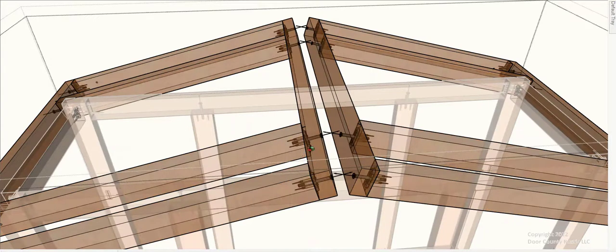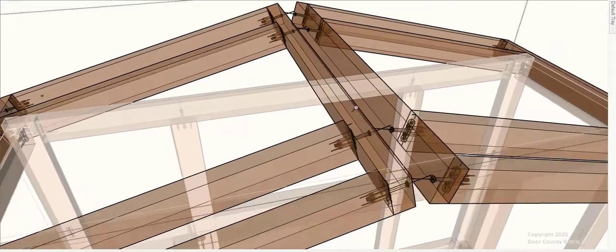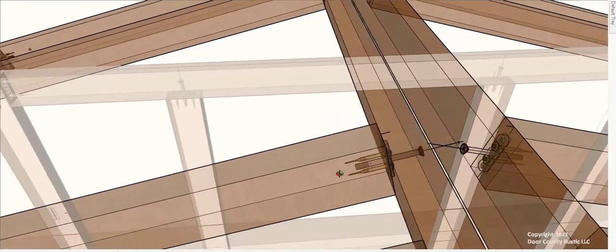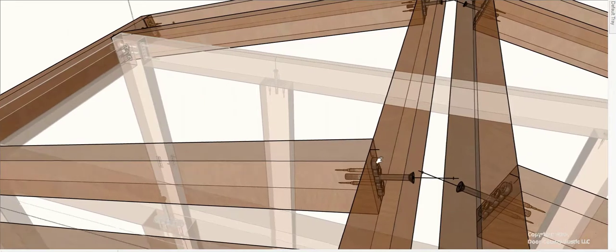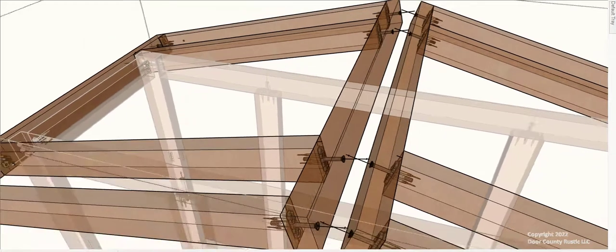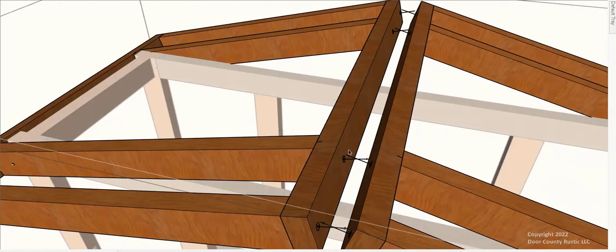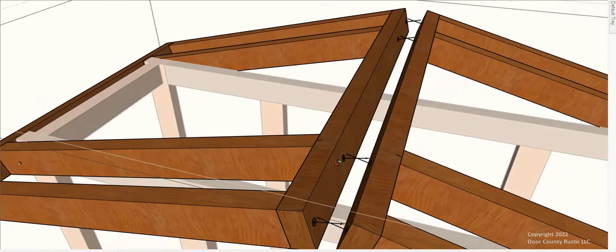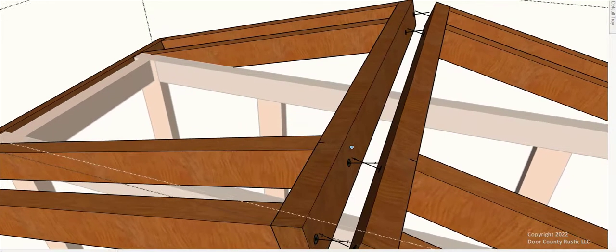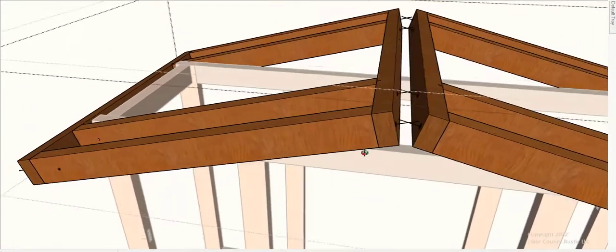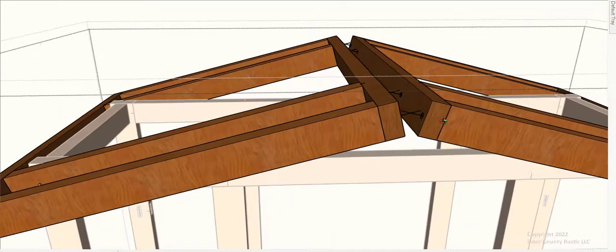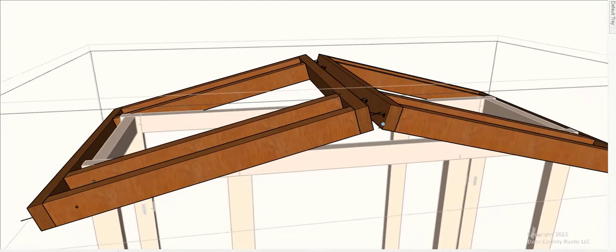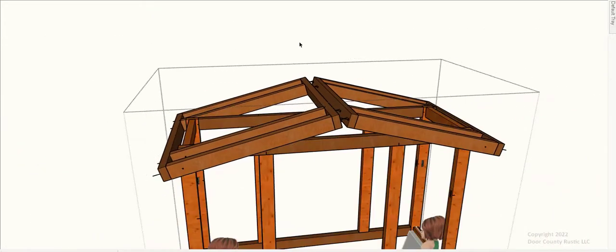I can. Okay, so if we look at it transparently, you can see that there's a bolt that needs to go from this side of the surface through and into the tenon that's mounted on the end of that. And by doing it with this space in here, that space allows room for a wrench to get in there to tighten that up, but it also becomes the space that is used for ventilation. That's a huge item on any kind of structure like this, that you want to get that airflow going through there, whether it be for human beings or for firewood or whatever.